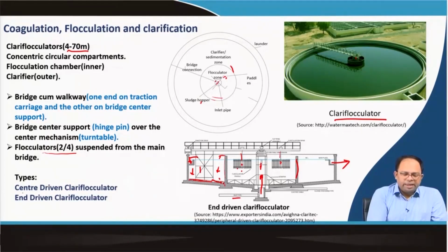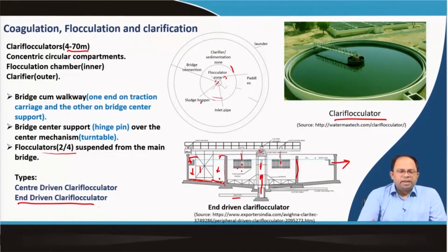There could again be center driven clariflocculators, where the bridge is rotated by a motor from the center, or end driven clariflocculators, where it is rotated from the side. So, this is the basic design of a clariflocculator. Like the previous one, this is another design, and it is a very common design which you can find in many of our water treatment plants.